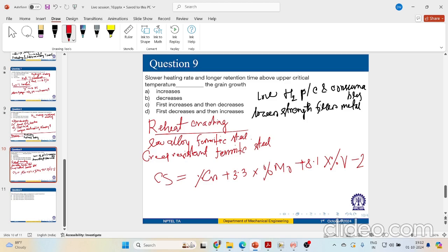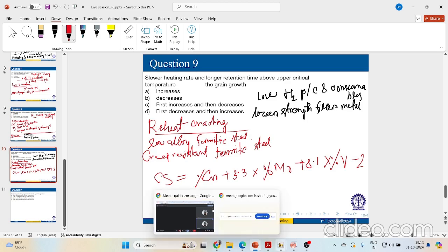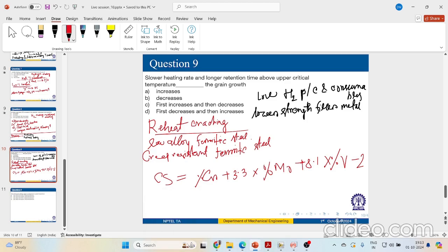Now, when the coarse-grained heat-affected zone is reheated to elevated temperature for stress relieving, fine carbides precipitate at dislocations in the prior austenite grain interiors. This is a bit confusing, and I cannot write down everything over here.